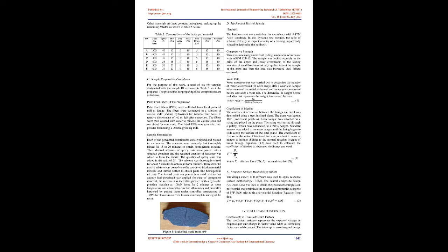Na01 to Na05. The developed pads are tested for tribological behavior under conventional environment in a standard pin-on-disc tribometer. It was observed that increase in steel wool concentration resulted in high coefficient of friction and low wear rate of pad as resulted in Na05 composition. SEM analysis of the wear surface has proved to be useful in understanding the wear behavior of the composites. Developed asbestos-free friction lining material from palm kernel shell.